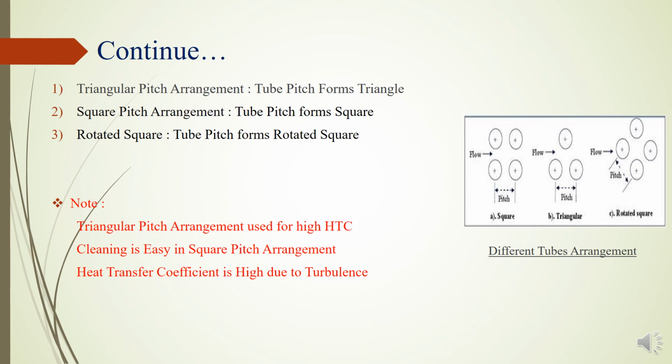It is better for heat transfer and surface area per unit length. So it provides a more compact arrangement, usually resulting in a smaller shell and the strongest header sheet for a specified shell side flow area. This arrangement is preferred when the operating pressure difference between the two fluids is large.